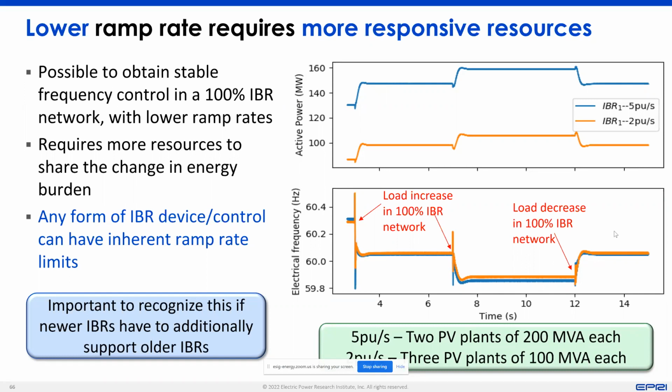So what we have seen is, depending upon certain type of motor load and how they react to a disturbance, especially let's say when the fault clears and they're trying to come back, at that point in time, they actually need both real and reactive power. And if you try to prioritize reactive power there or reactive current in that scenario, the motors may actually stall again because the load will drive the motor down.